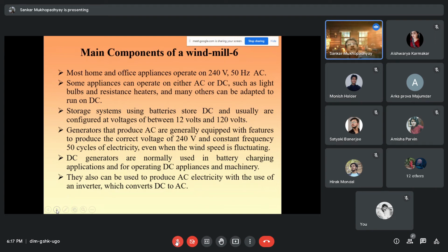Now, if the wind speed is very high, what happens is that instead of 100 to 120 rpm, it becomes 150 or something like that, because of the high wind speed and high pressure difference, and the speed has gone up. Now how to protect from this situation? What is done normally is there is a mechanical sensor. Presently, electrical sensors are also available.